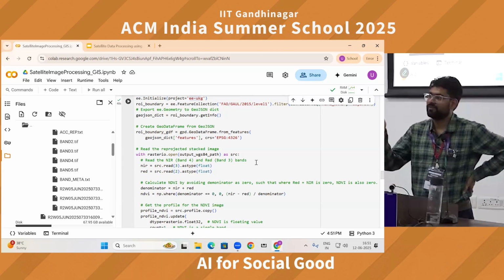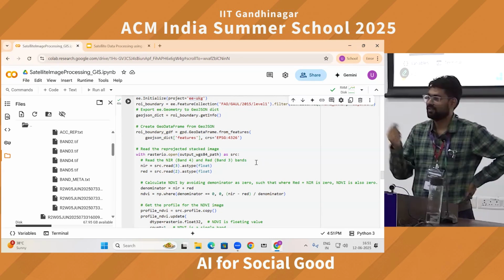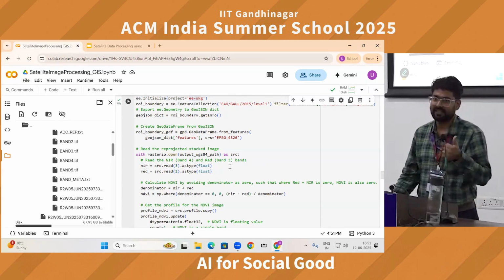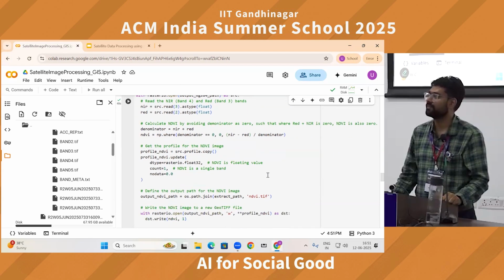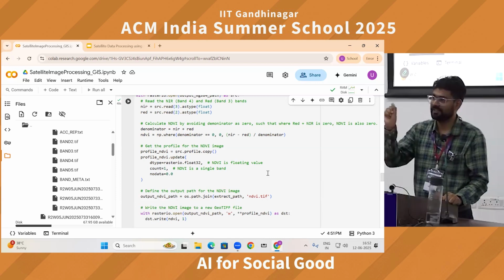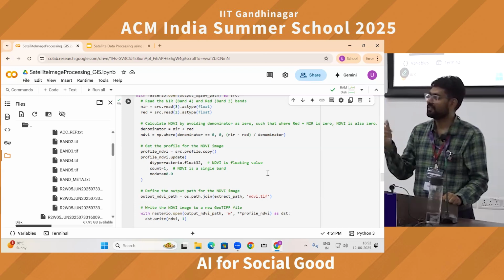First, what does the profile consist of? What kind of information? Band, yes. First, we have to change the band count. The second thing is the data type, because earlier the DN values were unsigned integer 16, but NDVI will be a value between 0 and 1, and it can be like 0.4326. So we have to change our data type.